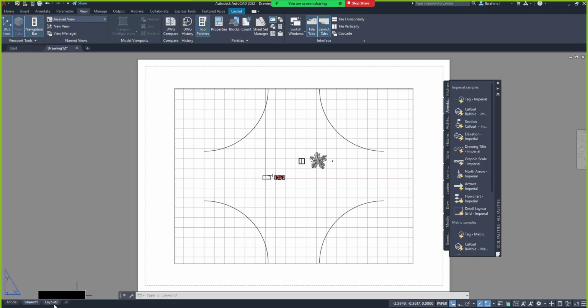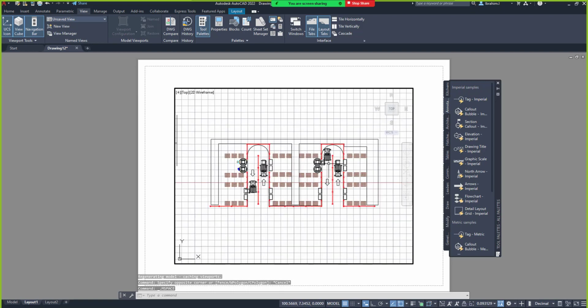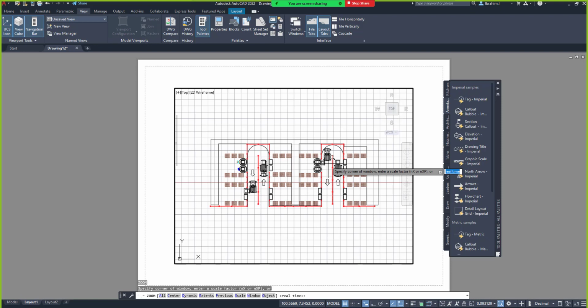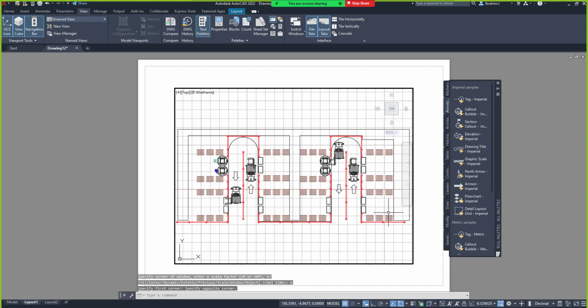And there are different methods of going to activate this section. We have the layout here already. If I want to increase the number of layouts, for this first layout, layout one, I can decide to enter into this design and zoom in on one of the objects in the workspace. Let's use this plan for example. I'll type Z, enter, W, enter, which is for window, so that I can create a window around my design. And then I click, and you can see this object around this workspace, right?